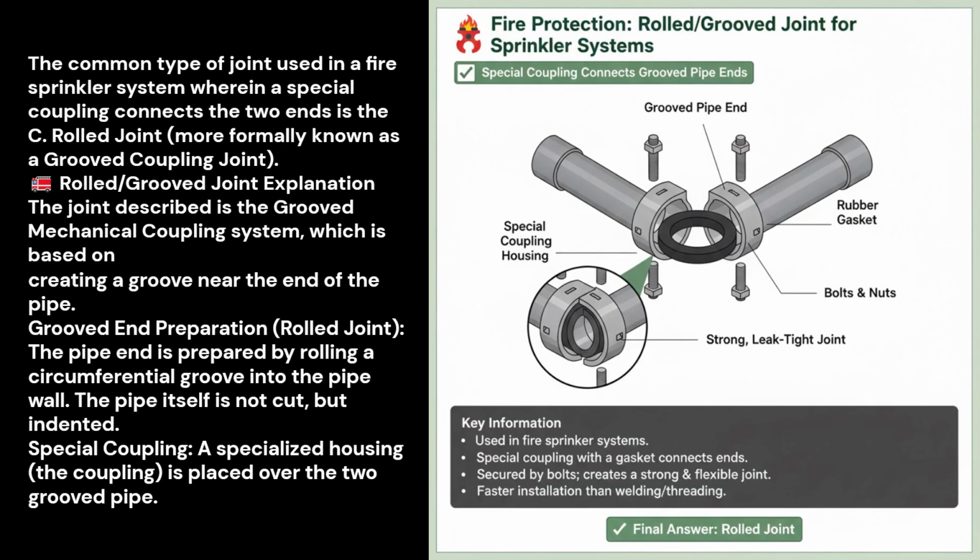In contrast, cutting a single hub pipe often leaves one piece with no hub, just a spigot on both ends, which cannot be directly connected in a standard hub and spigot system without an additional coupling, leading to more fittings, cost, and potential waste. Therefore, to avoid waste and maintain usability of both cut segments, double hub pipe is the preferred type to cut. Final answer, D. Double hub.